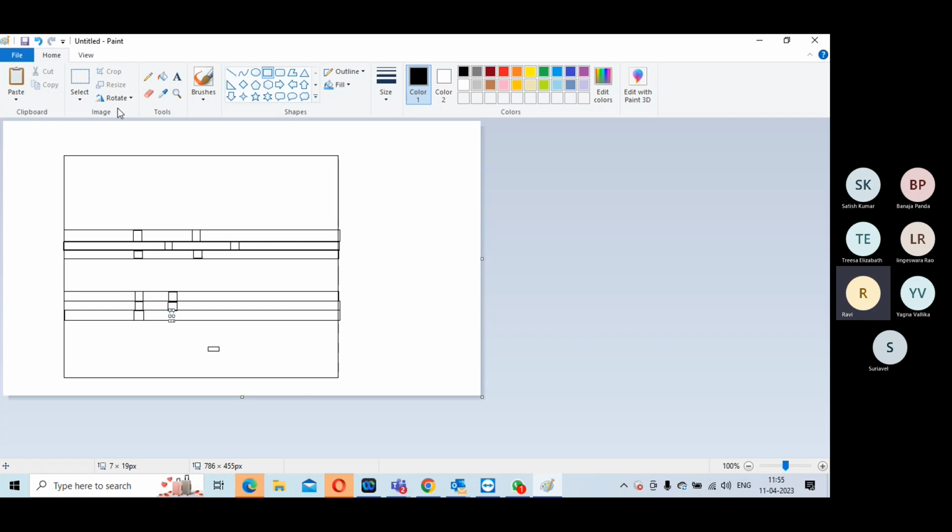At the time of fill, we have metal fill and base fill. I'm only talking about base fill. Base fill also has many sizes. You should enable all the sizes of base fill. Because if there is only one single width of base fill, your netlist size will be too big. So you should have multiple widths.